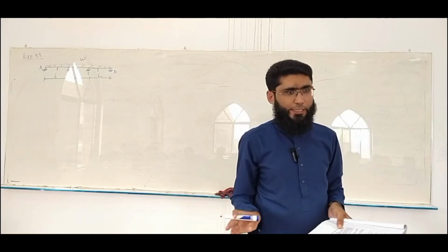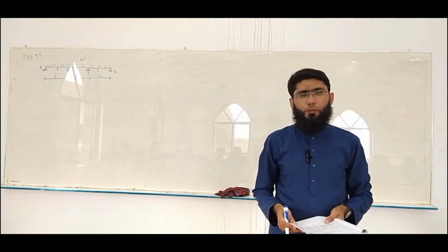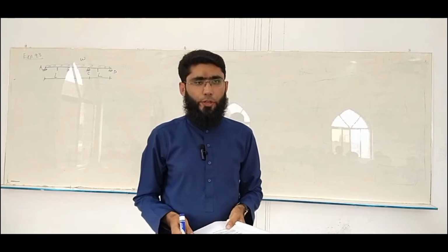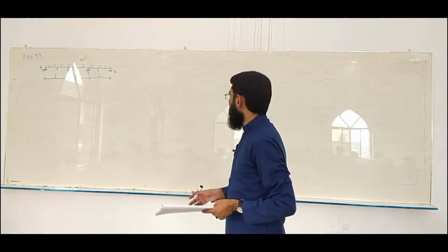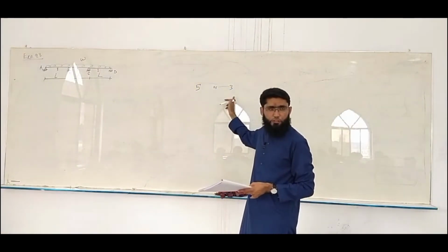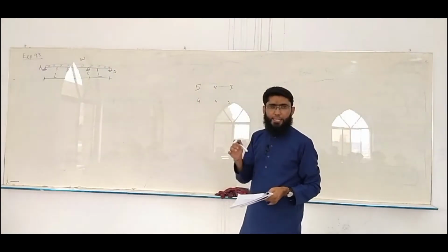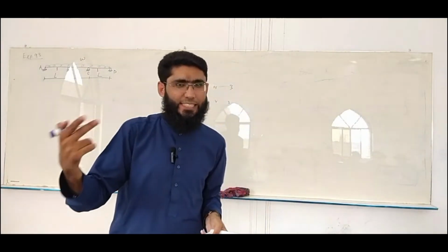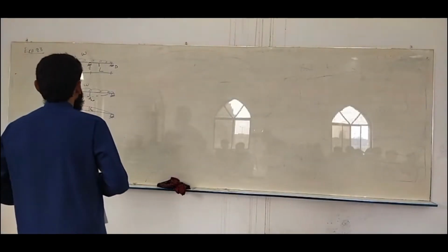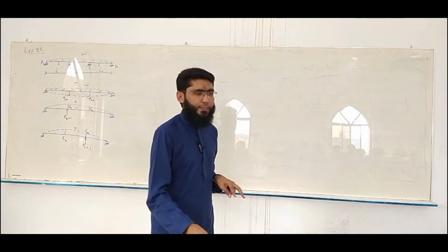So this is the continuous beam, and we are required to determine the reactions. It is subjected to a simple UDL. So what is the degree of indeterminacy of this beam? In total, you could say there are 5 unknowns versus 3 equilibrium equations, or you could say it is 4 versus 2. Again it is a difference of 2. There are 2 excess unknowns beyond the number of equilibrium equations. So there are going to be 2 compatibility equations in order to find 2 redundants.